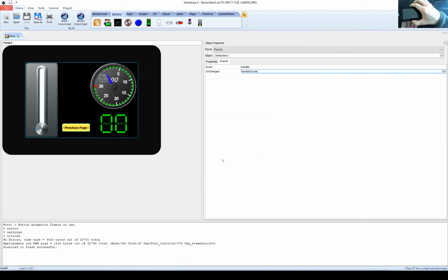And now you can perhaps see that it's stating that the drive is not mounted, which means it's searching for the graphics assets from the SD card. So what I'll do is put the SD card back into the module. And then I'll power up the module.